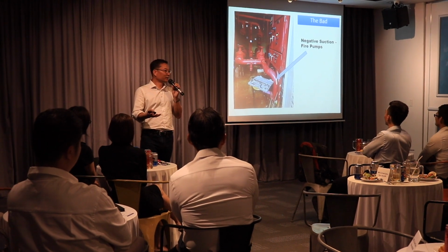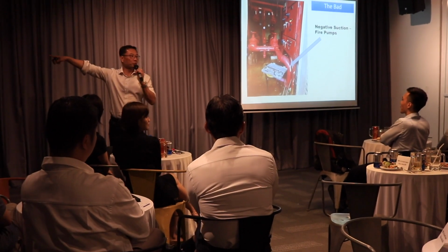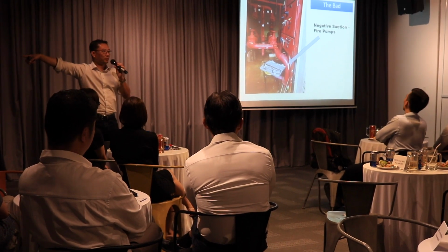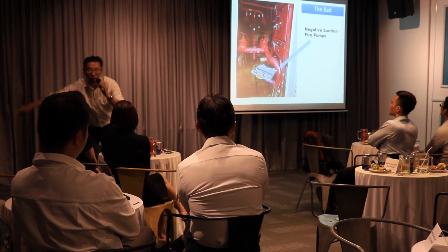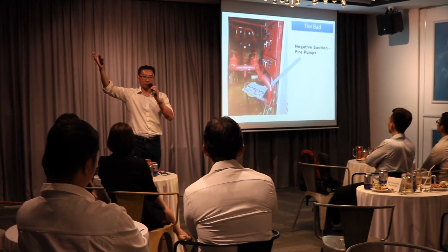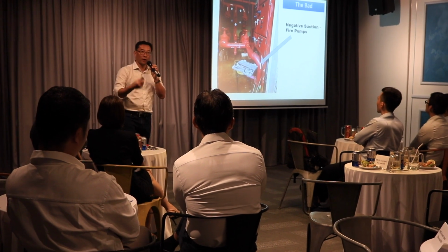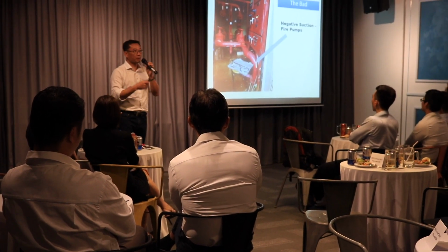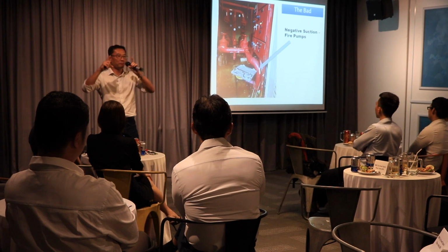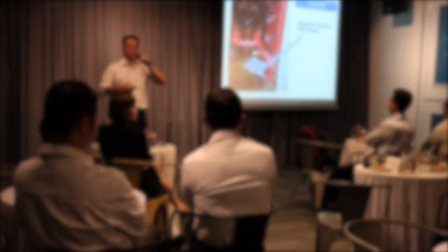I didn't understand, so I asked, can I see the tank? Can. We walked almost 200 meters away to see the tank, because the pipe was running below the ground. I said, oh, okay. Now I know why the problem. Because the suction here is negative, you have an NPSH problem. You open up the pump, all the impellers become this big, become this small, because they got eaten up.